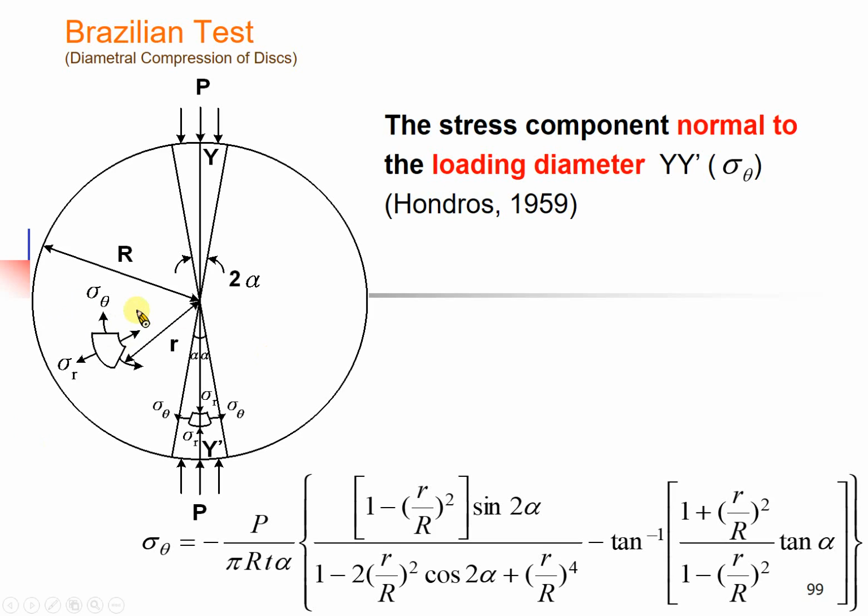It's totally the same. However, sigma xx and sigma yy are the rectangular coordinate system. This will be the polar coordinate system. That will be the same idea. So you will have a tangential stress tangent to the radius. Then you will have the radial stress parallel to the radius direction.